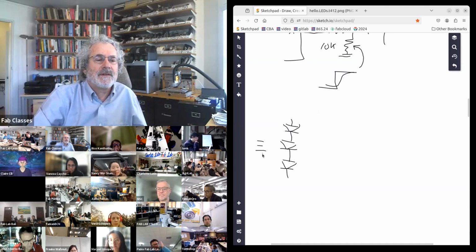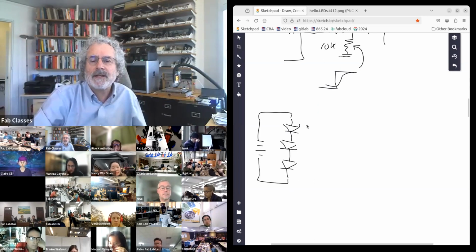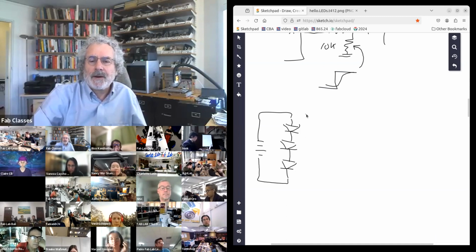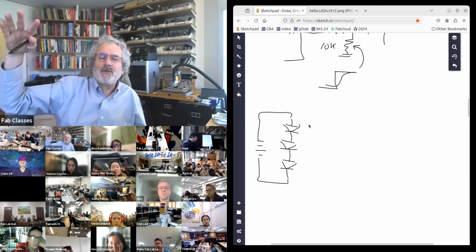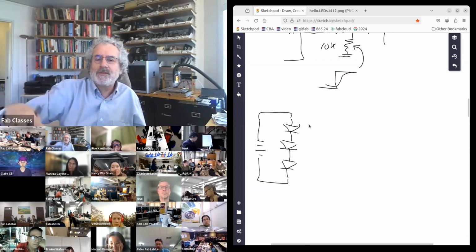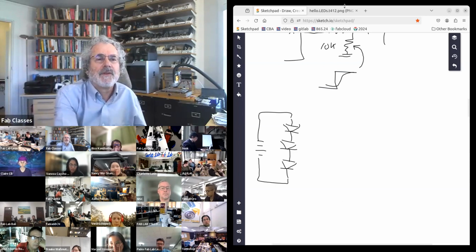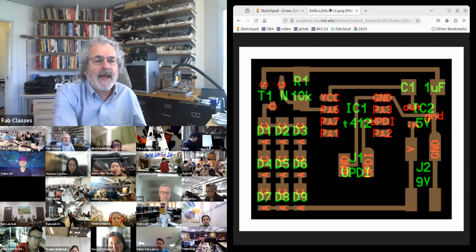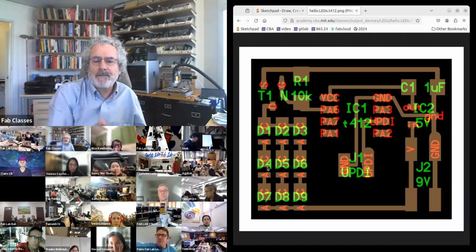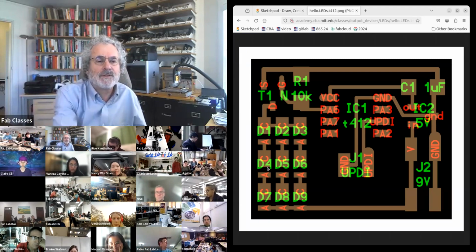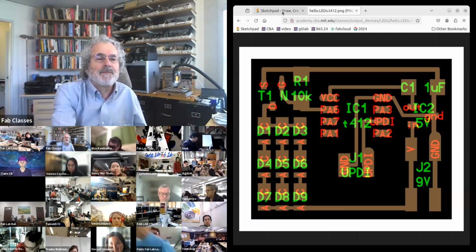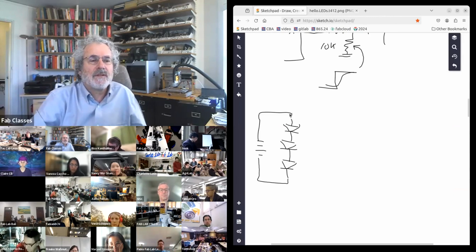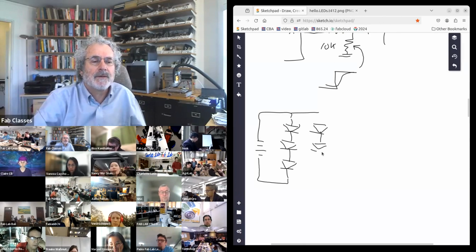If the diode drops add up to your power supply, you don't need a current limiting resistor anymore, because if you start to pull current and it droops, it automatically limits. So here what I'm doing is I'm stacking up the diodes in series to add up to my voltage drop. Then to add more of them, I'm making multiple strings in parallel.